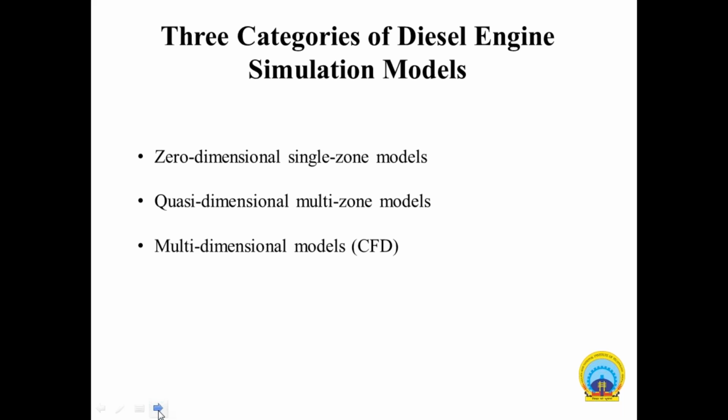So the RK model takes into account the conditions of evolution of each fuel spray and the near-wall flow generated by sprays, and also the interaction between sprays and the wall, as well as between near-wall flows formed by adjacent sprays. These features of the RK model allow prediction of diesel combustion and emission over the whole operating range for the following other parameters also, like piston bowl shape and sprayer location. Swirl intensity is also there. Then diameter and number and direction of sprayer nozzles, the injection profile shape, and any multiple injections.